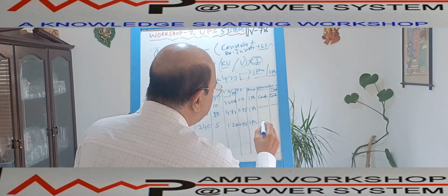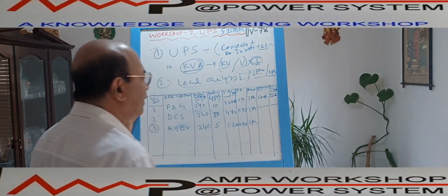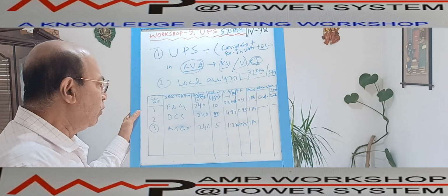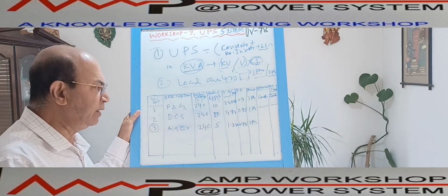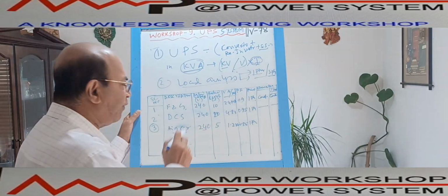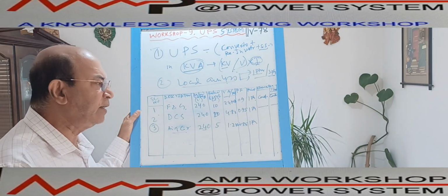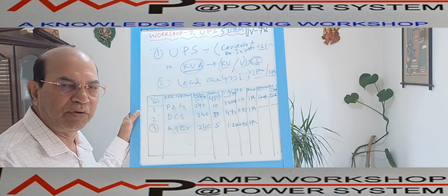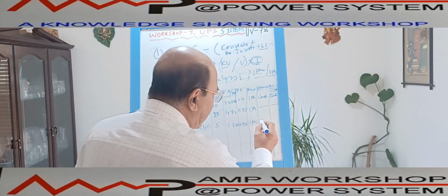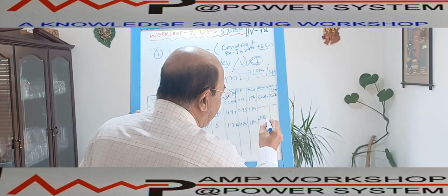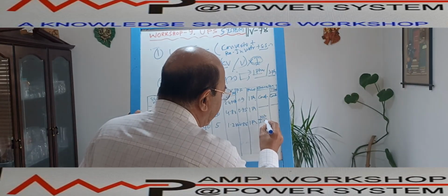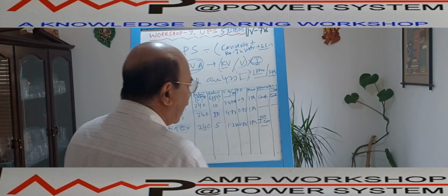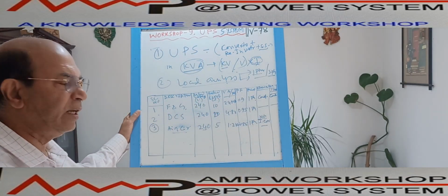Now the characteristic of this current: it is not constant, because when the motor starts, it is a motor. Running a fan in the air circulation system means it is a motor. The current is not constant. There is an inrush current during starting. And we have to note the duration of the inrush current.